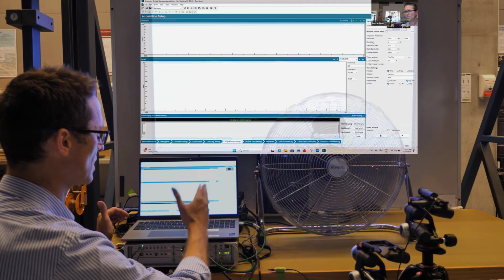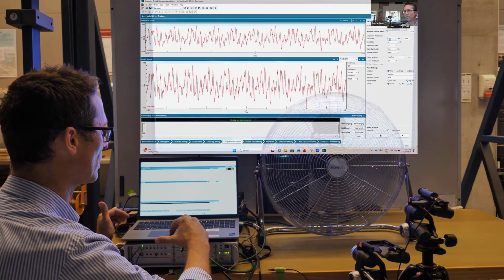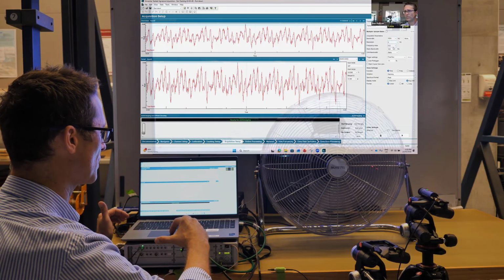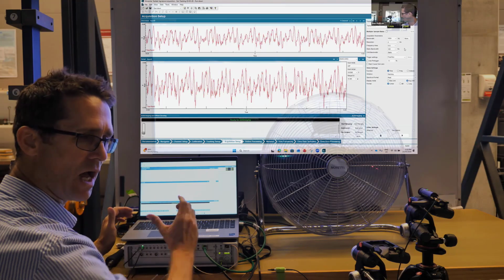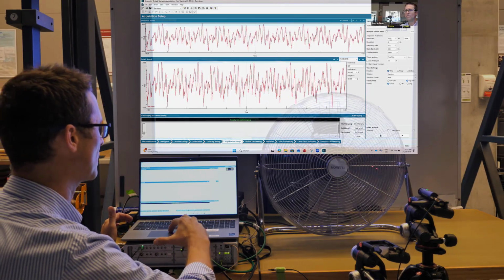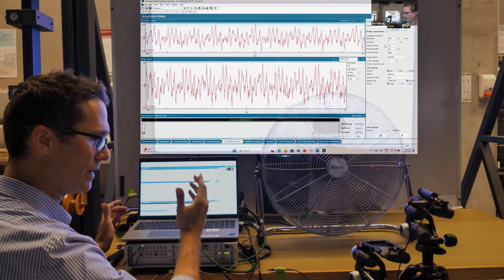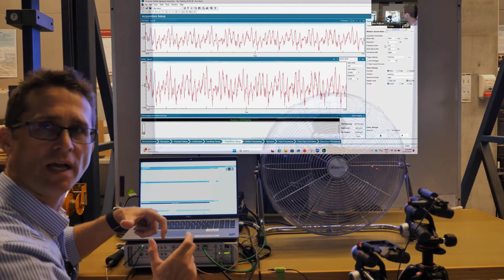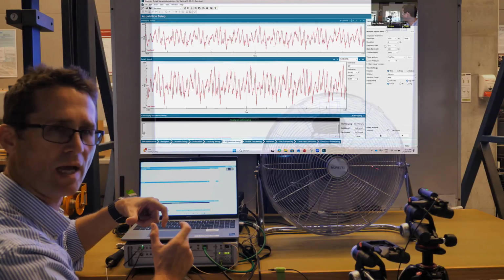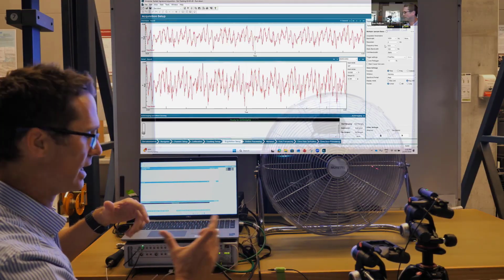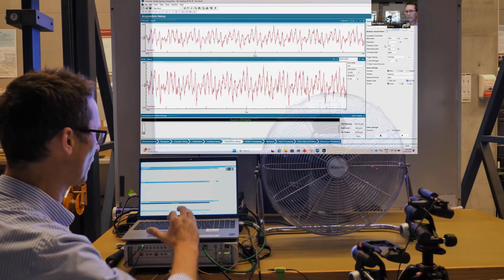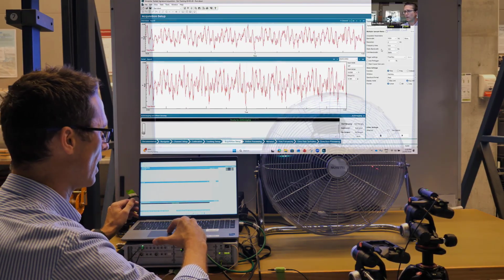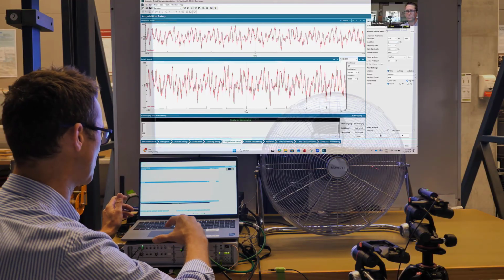So in the acquisition setup sheet, I've defined a bandwidth of 1024 Hertz with a resolution of 2 Hertz. That's 512 lines. That's going to result in half a second per FFT. So if this ran down very slowly, those half seconds would be quite heavily overlapped. If it runs down more slowly, then I can potentially have even finer frequency resolution. But I found that half a second with 2 Hertz resolution is reasonably good.